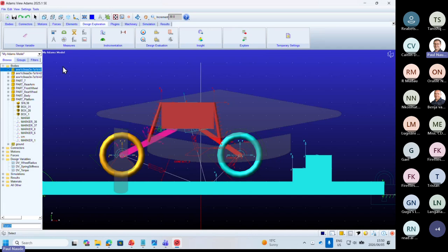But if you now have a CAD file that consists of 20 pieces just for the body, and you're going to import it, it's going to want to create 20 parts for each one of the bodies that's representing the body. So be careful, don't waste parts on bodies that are connected and don't move relative to one another. For instance, this ground for now.